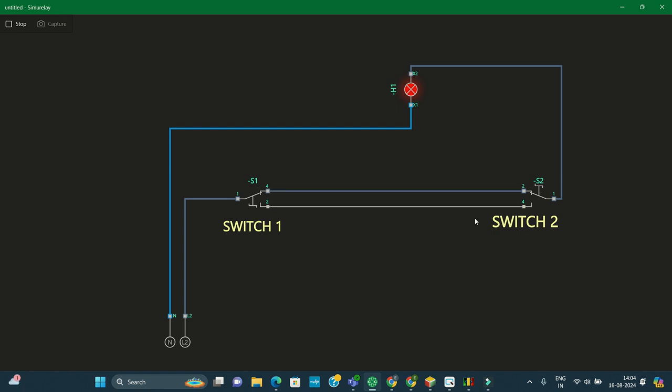When you get to the second floor and you want to get rid of this bulb or anything, you just press here and it stops working. And the reverse is true. When I'm here and it's open, I can switch on from here, and when I reach the down floor, I switch off. So this is the way the power is flowing in this kind of system.